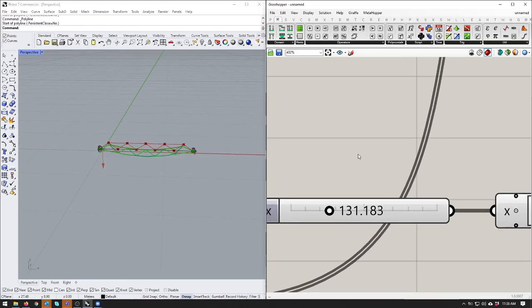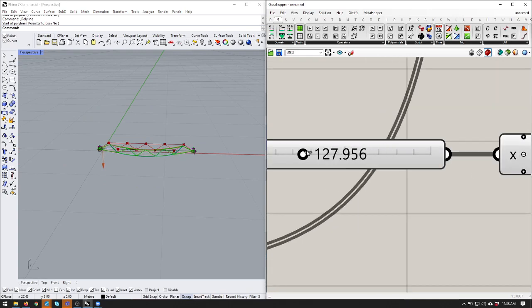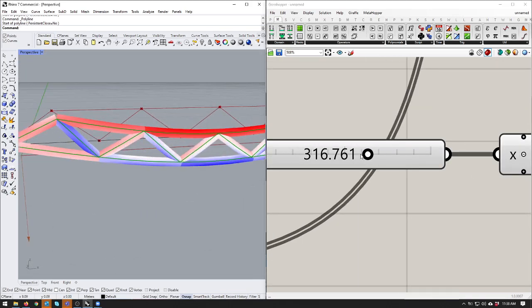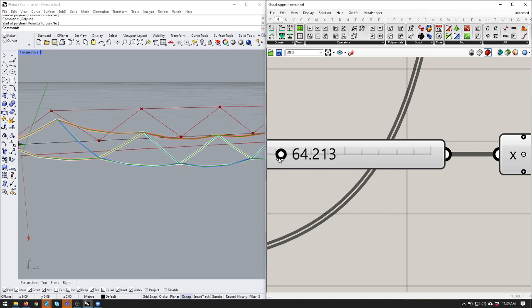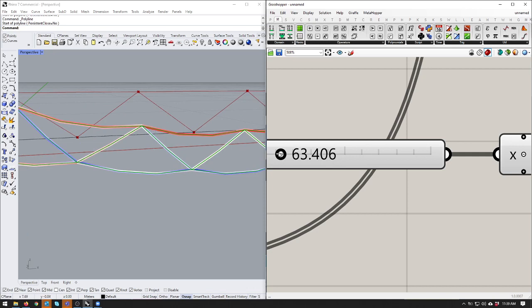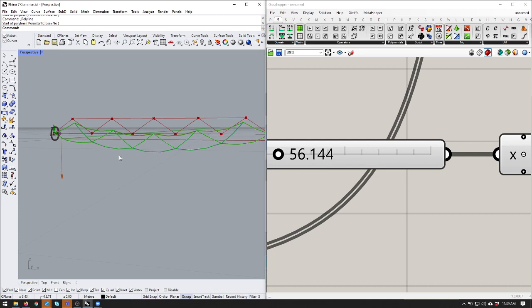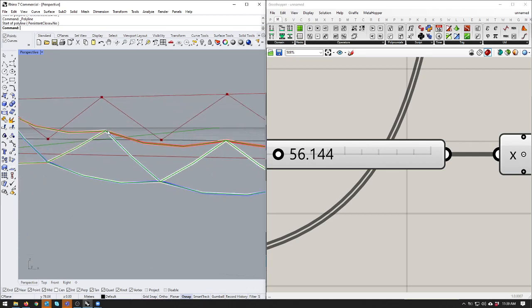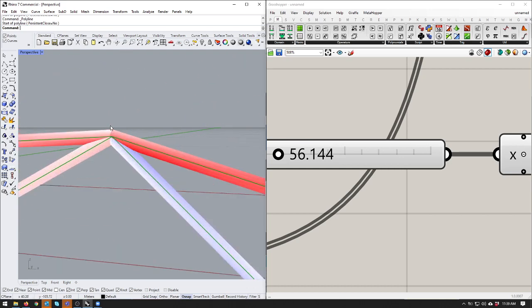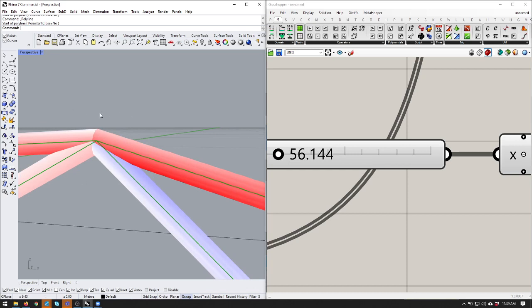Are we all good? So look, we're actually seeing that when we set this thing to deform, as it gets thinner and thinner, the overall structure isn't deforming. The truss is actually keeping the thing slightly rigid, and what we end up seeing is that the members deform from node to node, because these are rigid nodes, right? You might want to start sharing again. Sorry, my bad. All good.